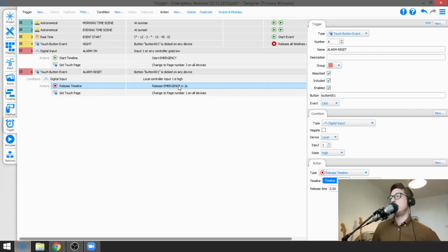So no is the honest answer. You can power Pharos in two ways, and I have seen people sometimes make this mistake, and it's not recommended. But you can power Pharos with either PoE, power over Ethernet, or you can power it via mains. You cannot power it via both, or you shouldn't, because you could potentially short the device.